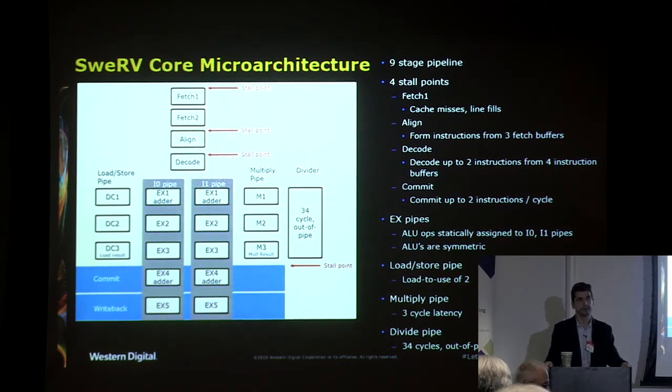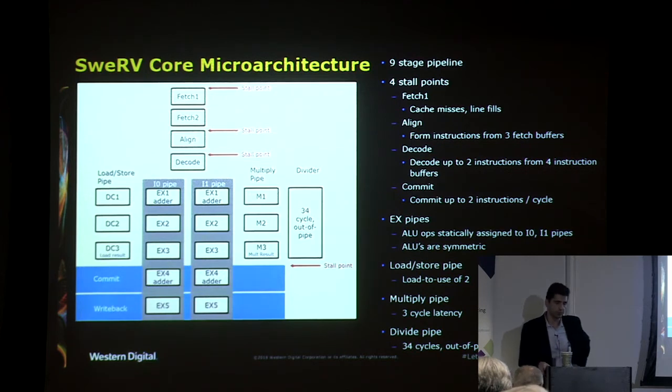There are other types of interrupt, like traps or exceptions, where your instruction itself generates an exception, like a load that has a miss. In that case, it's different. So one should make a difference between an external interrupt versus one the program instruction generates. Correct. I'm just agreeing with you. Those are all fair comments.